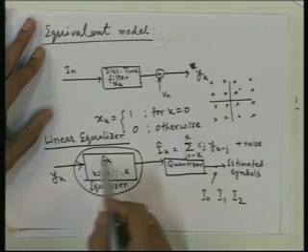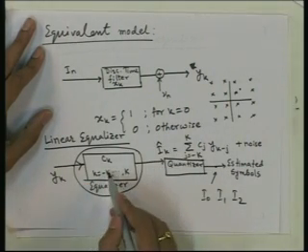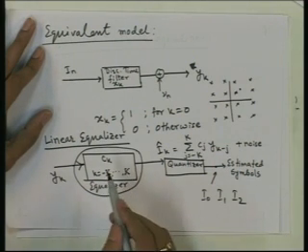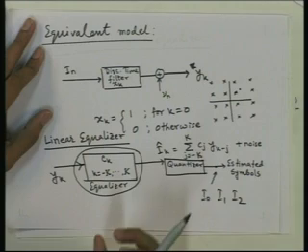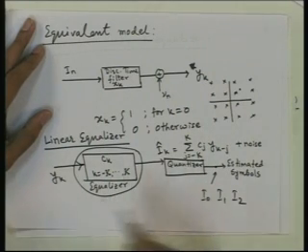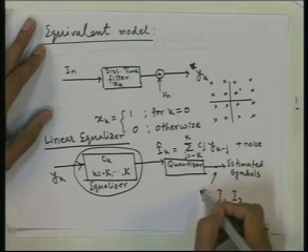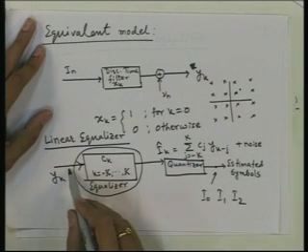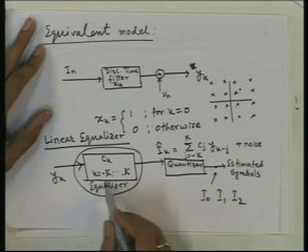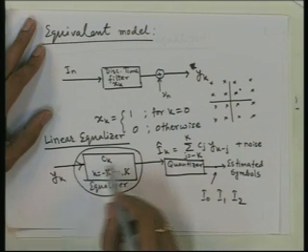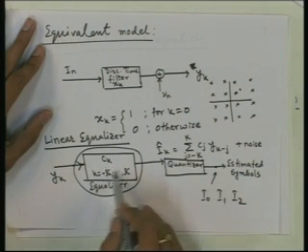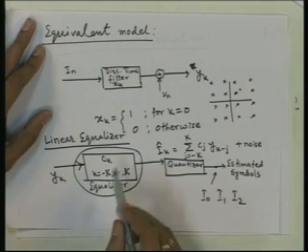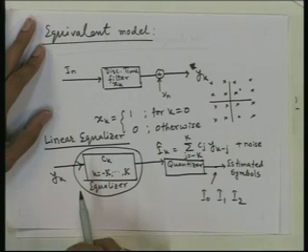And so, possibly we will need a smaller length filter, because this k itself is also a parameter which determines the complexity of the equalizer. We would like to have as small capital K as possible. So, if we cancel the effect of previously detected symbols from the incoming signal, then it may be possible to equalize this stream with a smaller length filter here, whose job will be now to cancel the effect of future symbols from the past symbols only.